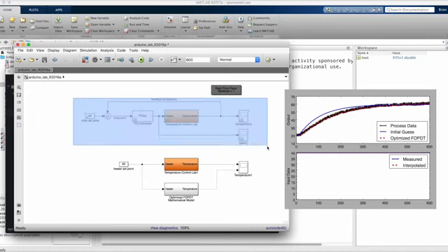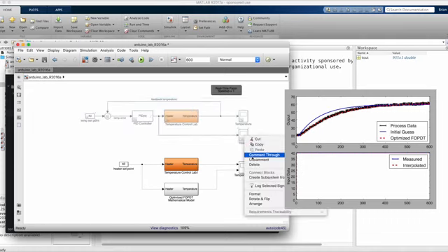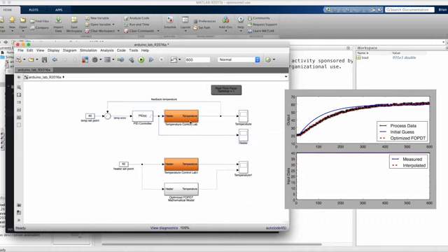Designing a control system is usually an iterative process, and that's what we did here. We went from open loop to bang bang to PID without a model, to developing a model which will allow us to quickly tweak our PID gain, or develop a more optimal controller. Okay, I know this video was really fast, but hopefully it still gave you a better understanding of how to just jump into a problem and make your way through some of the confusion that you might have. Also, how control system theory is tied back to the larger engineering problem.